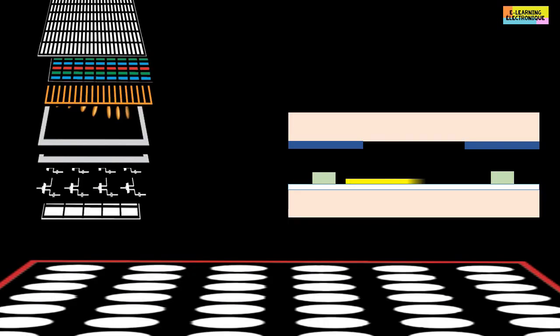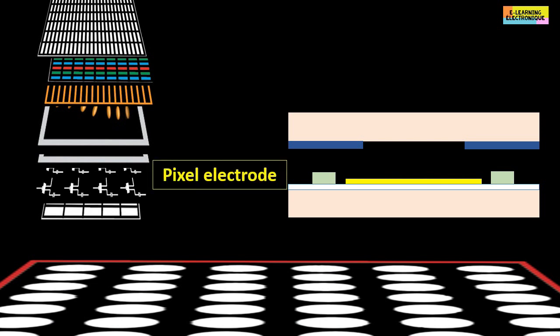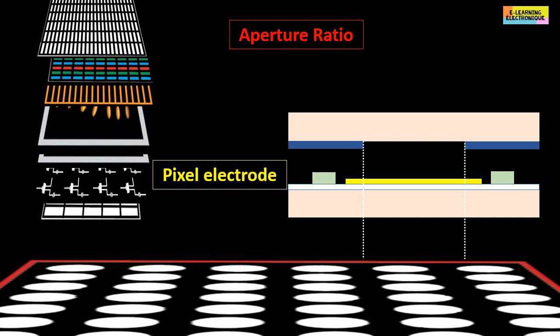This concept of passage of light through the various structures to illuminate the subpixel is called aperture ratio. On this figure, we see on the cut the superposition of various elements of the screen, some of which are opaque to light, as the electrodes of TFT and storage capacitors, the vertical lines of the data and the material of the black matrix. The aperture ratio of the pixel, represented here by the red arrow, is calculated by dividing the surface of the opening of the pixel by the total surface of the pixel, represented here by the black arrow, and which includes the pixel and the opaque elements.